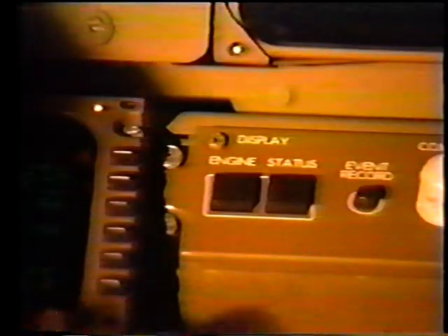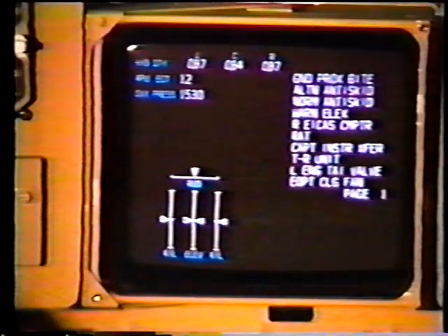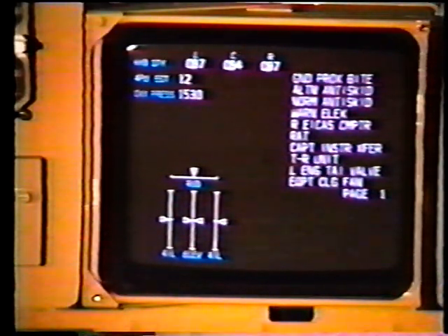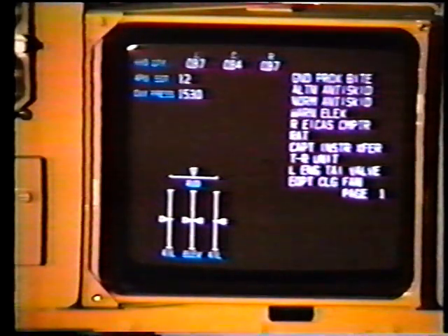Status of various airplane systems can be shown on the lower CRT. If new status messages occur when the status page is not displayed, the status queue will appear in the upper left corner of the lower CRT. Pushing the status switch will display various system quantities, pressures, and minimum equipment list-related status messages. Also, primary control surface positions are displayed.